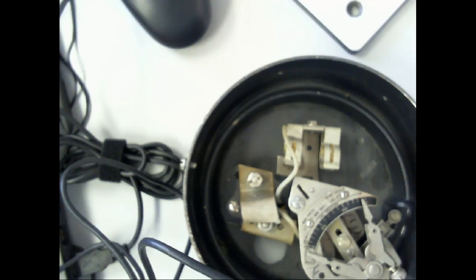When you put that in water, we worked at a place where they made big old generators, and they wanted to check the current output on them, and they didn't have a resistor that would work. So they got a big old plastic vat, and they filled it up with distilled water, and then they'd put the two outputs of the generator on there, and they'd start pouring salt in, and they could change the resistance that way. They had to get pretty high because eventually, I squared R, the water would start boiling.